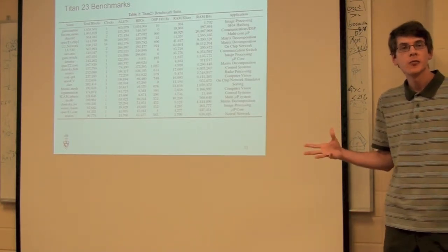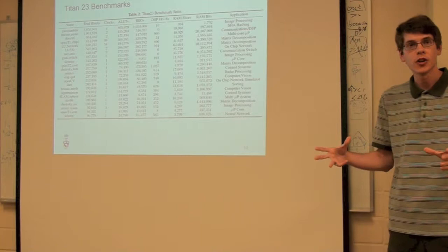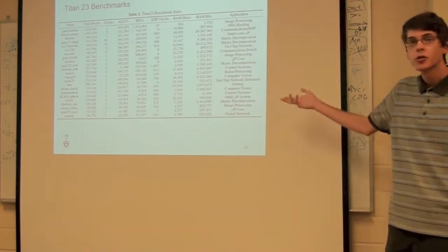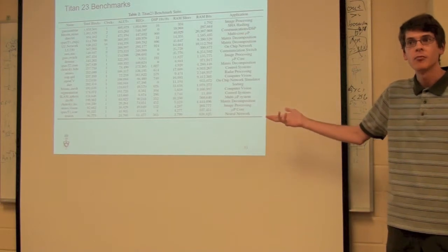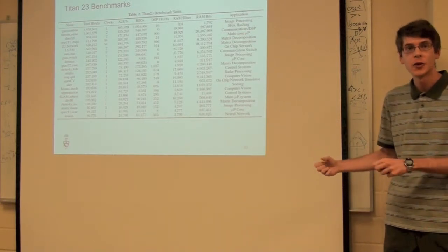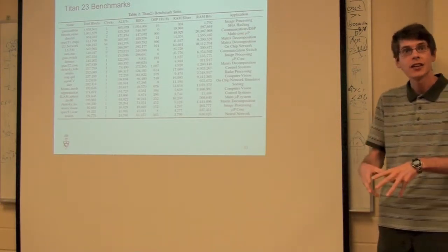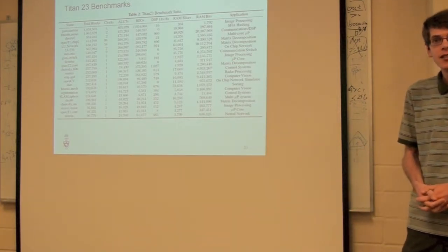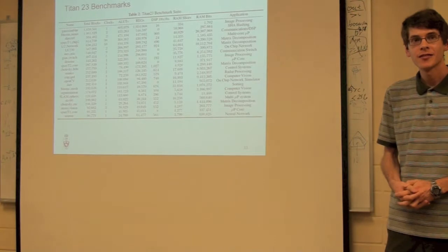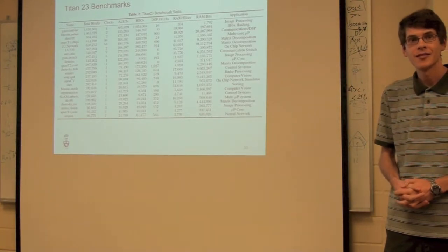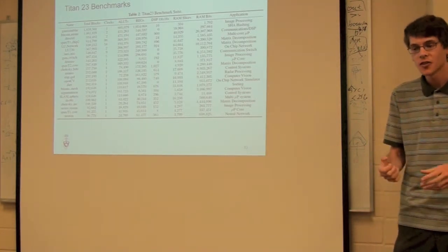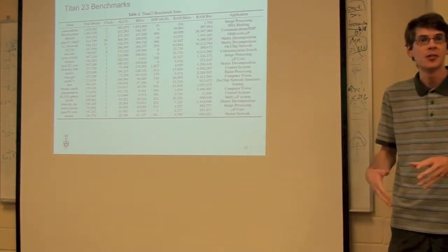Historically, VPR was built to really try and minimize the number of clusters, and when you move to a more flexible architecture like Stratix 4, that can start to hurt your wire length because you can pack things very tightly, which may not be the best. I wonder if there's some simple way to say, these repulsive functions, that repulsion is greater than this, just don't do it. Well, yeah, ideally you want some kind of natural clustering to develop. That's a hard problem.